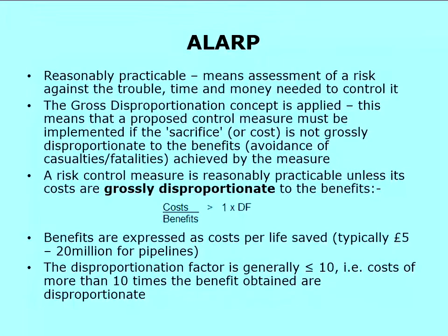You've got to notify them, which means you've got to provide information to the regulator and local government organisations as to where the pipeline is and what pressure it's at, etc. You've got to prepare a major accident prevention document explaining how you're going to prevent accidents. You've got to have emergency procedures and arrangements in place.